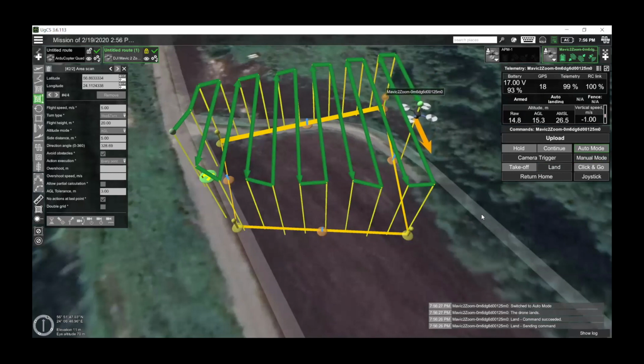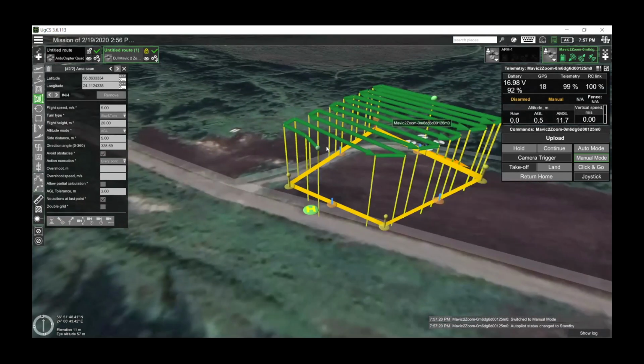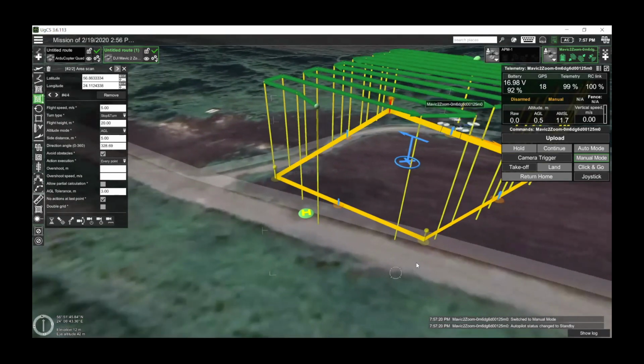The reason why it's recommended is because for all DJI drones, the flight calculation is pretty complicated, and one of the parameters which the drone knows for sure is the altitude of the location where it performed takeoff. If you perform the takeoff from a location different from the first waypoint, and this location has a much different altitude than the ground level of the first waypoint, there are possible safety risks. The application is recalculating this, but like any calculations, there are security risks, so it's strongly recommended to set this waypoint as close as possible.